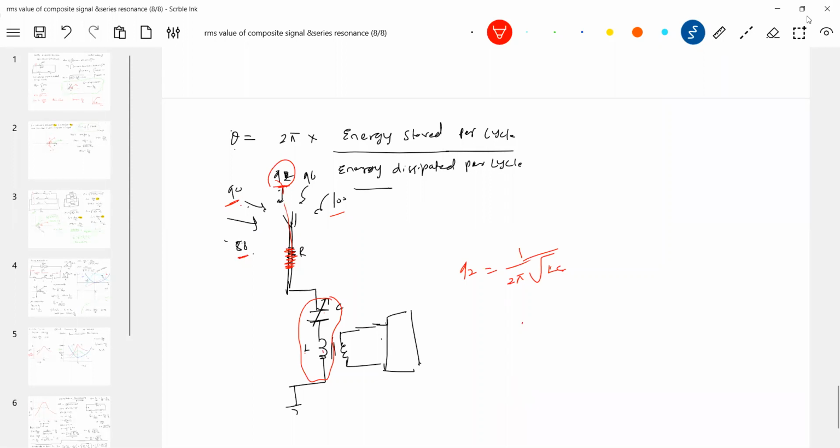What about this 90 megahertz? A signal will come and strike the antenna. Then the current due to this particular frequency signal will be very less because it's not at resonance. So the current will be maximum only when the frequency of the incoming signal becomes equal to the frequency of the circuit. Now this is a circuit, and what is the source? There are 5 sources: S1, S2, S3, S4, S5. It is as good as 5 sources applied to the circuit.